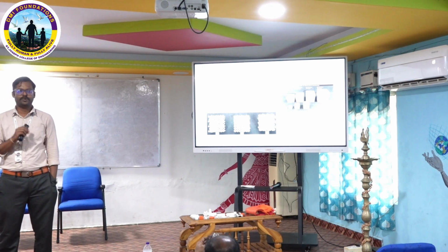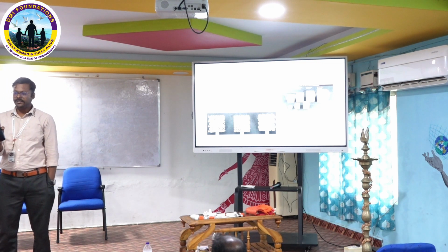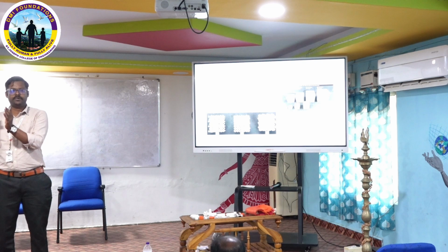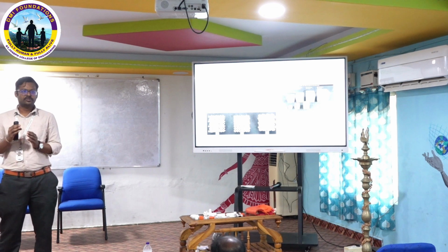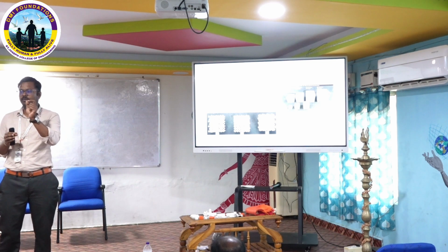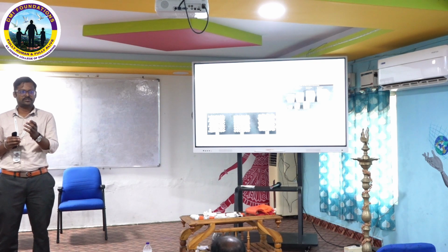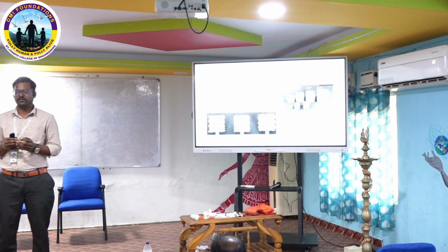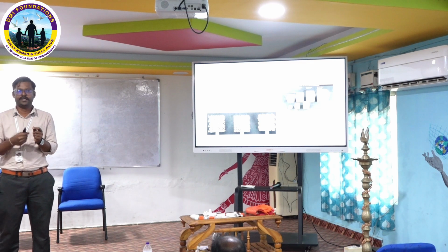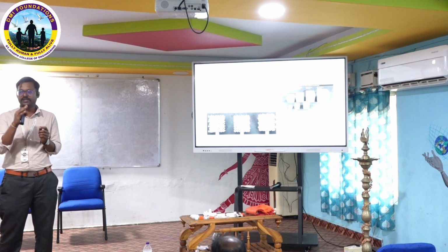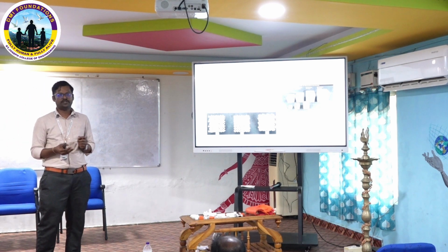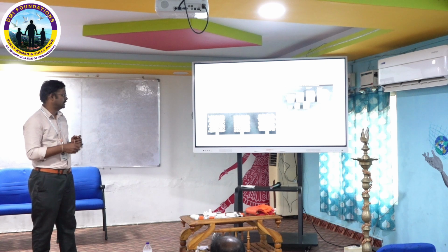If you go with additive manufacturing with a powder bed fusion process or any other technique, we have to consider the minimum feature that can be printed or fabricated by that particular additive manufacturing process. If I am going to use FDM technology, the dimension should be a minimum of 1 mm. For SLS we can achieve 0.8 mm diameter, but during post processing it may break, so we have to consider a minimum of 1 mm for SLS also. For DMLS we can go with 0.5, 0.6 mm diameter. Those things we have to consider in this section.